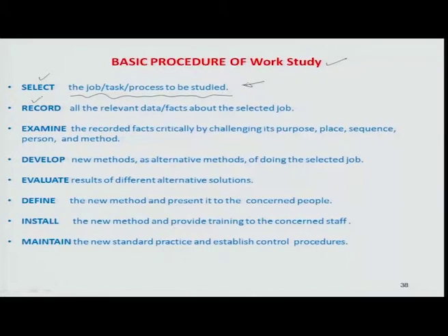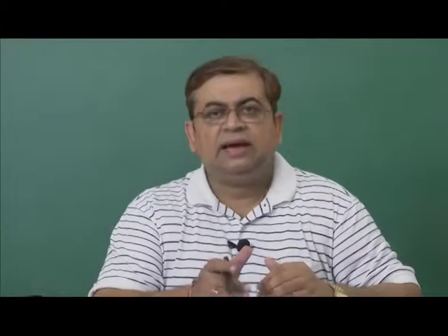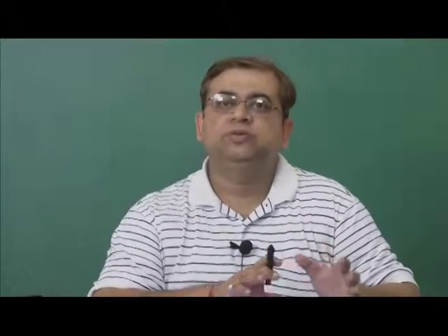So then the question of recording comes, that once these tasks have been identified, then you have to in a very organized manner record all the relevant data which is associated with the task. And in fact, when we talk about time and motion studies, here is where a lot of methods are used for recording the motion sequences involved in a certain task, or even the time scales which are associated with those motion sequences, or in fact trying to indicate motion sequences where some motions contribute to the overall task in terms of value addition, some motions are always there by the necessity to have them, but they are non-value adding, or there are certain motions which slow down the primary motions which would be able to achieve value addition to the product, etc.